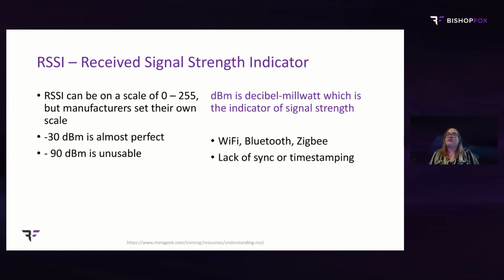So Wi-Fi, Bluetooth, Zigbee, they all use RSSI. Bluetooth, again, being used for tracking on purpose, will use the RSSI to determine how close you are to your tracked Tile or AirTag. And it does have a lack of sync or time stamping. So it is not perfect. It cannot be used in in-depth ways to track someone, but there are other methods that can do this.